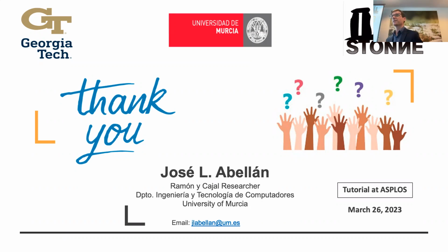Okay. Go ahead. In your simulator, if I want to use some other compression mechanism, rather than CSR or something like that, is it possible to model that kind of thing in your simulator? Yeah, absolutely. In fact, we have incorporated into the STONNE simulator bitmap, CSC, and CSR, and others could come; we need to implement that, but the extension can be done perfectly from the perspective of the memory controllers.